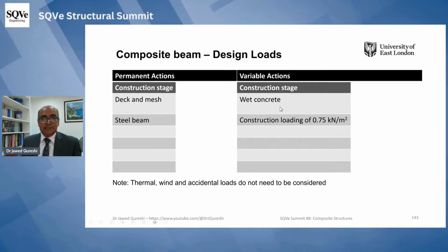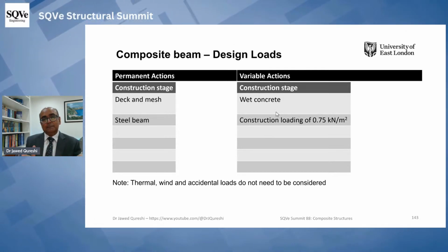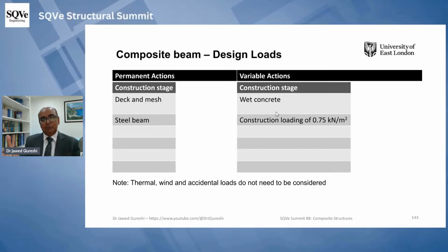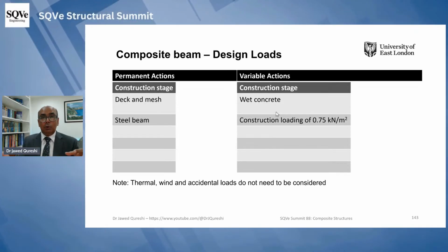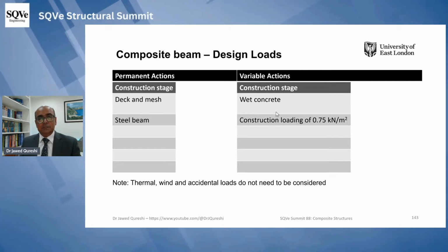So when you are checking the sheeting, you have to work out loading based on this, and then work out its moment, and compare that moment with the moment capacity, which I showed you earlier for the multi-deck 146 millimeter decking, which was from the manufacturer, or you work it out yourself using elastic and effective properties.